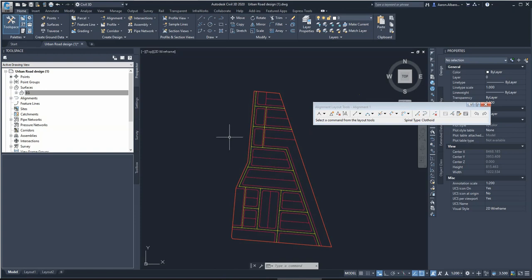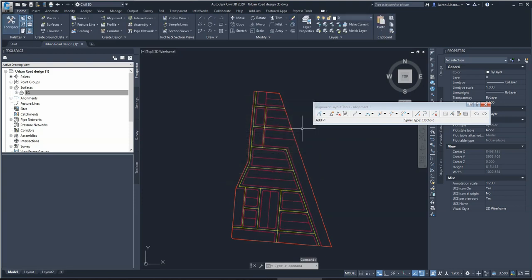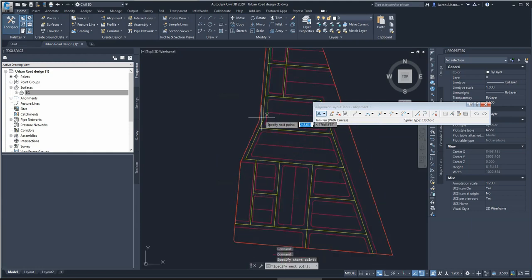If we don't have any, which usually you would by consulting with the council for that area, they should give you all these details. If we don't have those, if we choose something from 12 meters to 15 meters, that should be suitable. So I'll be choosing a radius for the horizontal alignments of 12 meters, as you can see here. And I'm not worrying about applying the formula and calculating the radius for that. So I'll be choosing that and choosing alignment with tangent with curves.